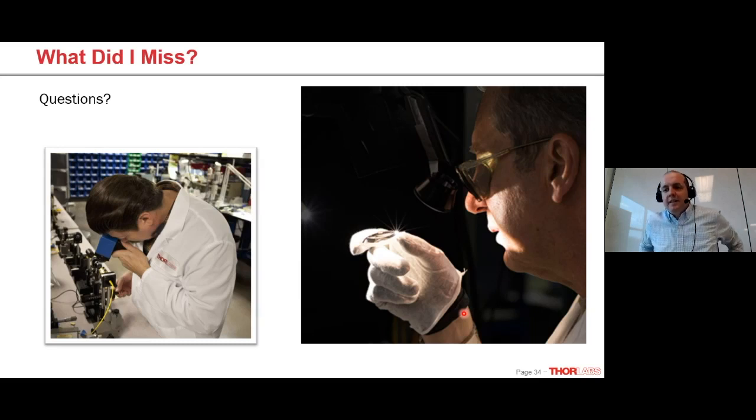So certainly a bit due to time, but also just a little bit of understanding that as we pass through these surfaces, if we don't have it perfectly flat, we'll see deformation to the wavefront, and this can really lead to either your image not appearing clearly or, more drastically in cases where it's an interference-based system, we're not going to see the effects that we expect. So that's certainly a big aspect of why we need to have a very flat surface.